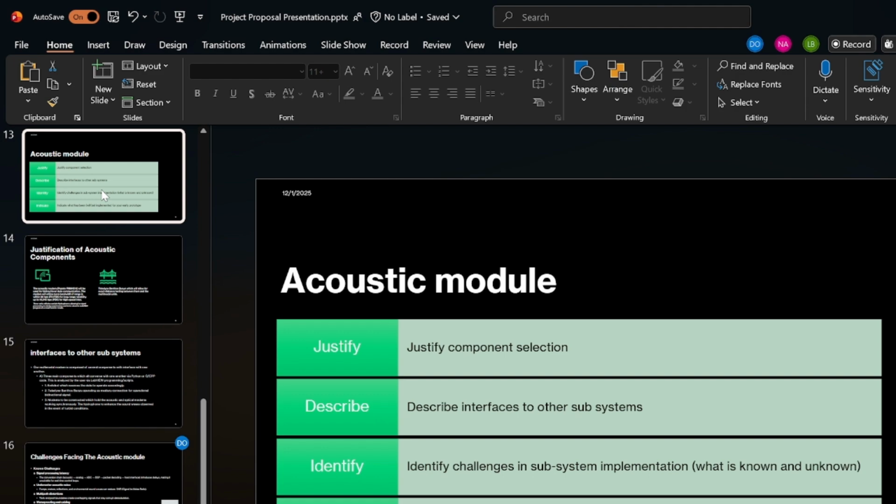We also incorporated hydrophones as part of our acoustic testing and analysis workflow. Hydrophones allow us to observe acoustic channels more directly, which supports signal processing tasks such as evaluating noise levels, interference, and wavelength clarity. The goal is to bring that data into LabVIEW so we can visualize and interpret what's happening during transmissions. This helps us validate whether issues come from the environment, the transducer's path, the configuration in modems, or the way we're handling the data upstream.